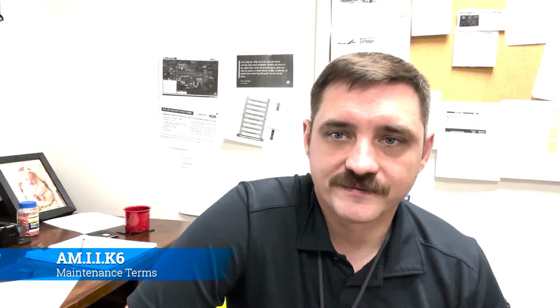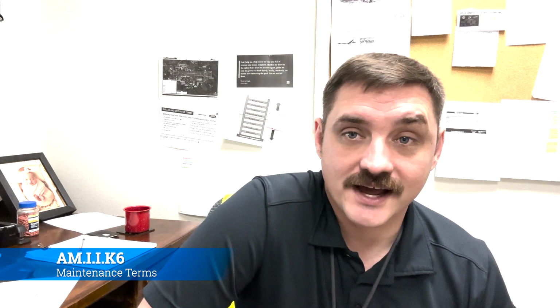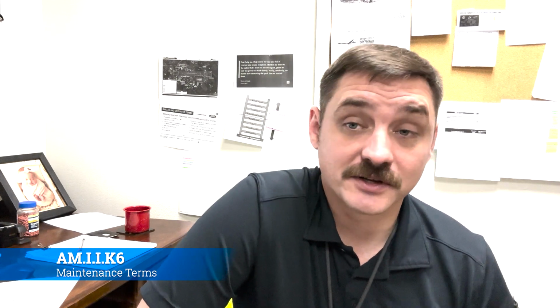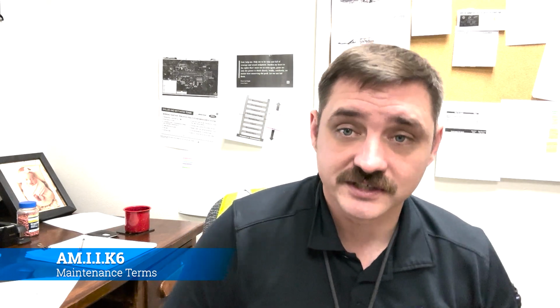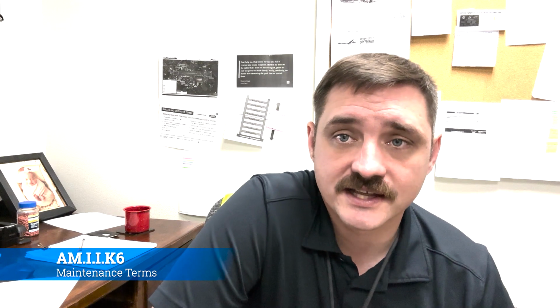Over time, you kind of get to know. You'll get a sense of what is significant and what's not. For instance, if the lav light is out, I don't think that's a significant system. It could be, depending on the agreement that airliner has. But you would want to go to Chapter 25, look at it, and say, okay, well, that's not on the MEL, so we can just defer it for maintenance. But if it is on the MEL, that means we stop and actually start to work on that problem right then and there, because that takes that aircraft out of service.